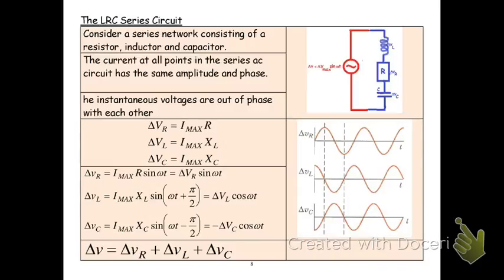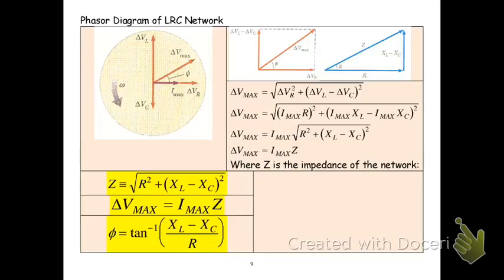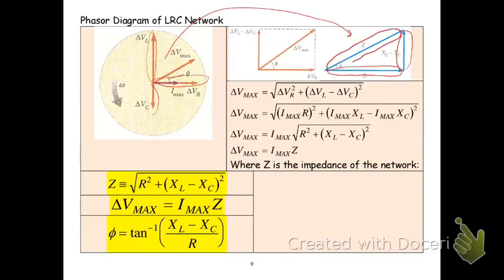That's very strange. You can't see it very well here. This is three voltages and there's some weird stuff going on, but what we get is we start trying to add up our voltage across my inductor and the voltage across my capacitor and the voltage across my resistor. And what I find is, because of this, I get my inductive reactance and my capacitive reactance and my resistance. And I can work out an impedance for the entire circuit.